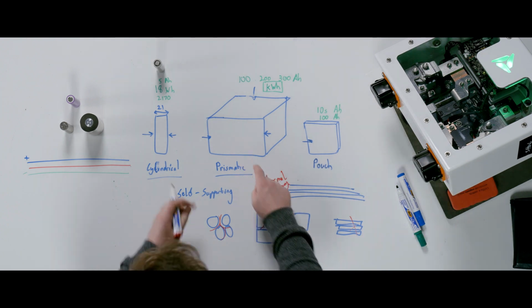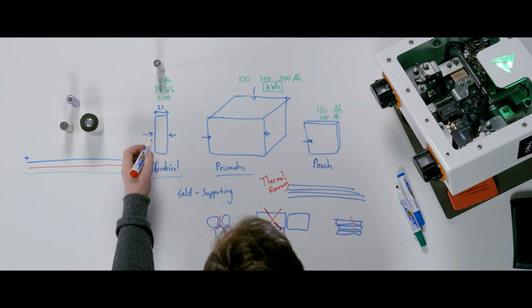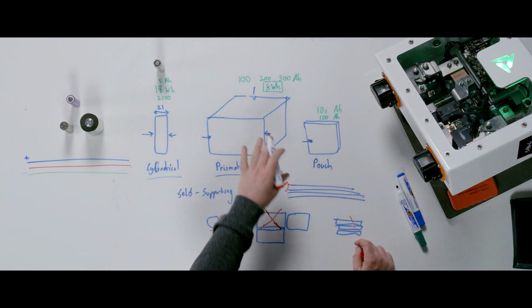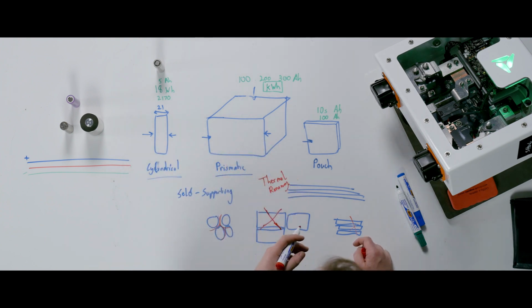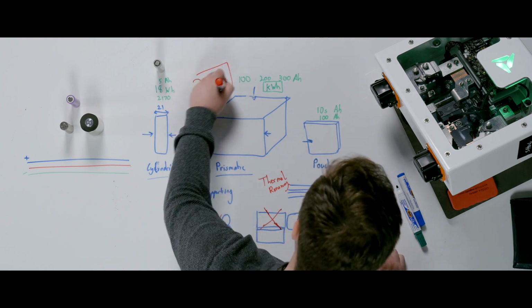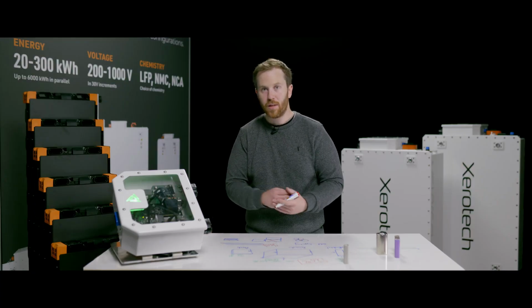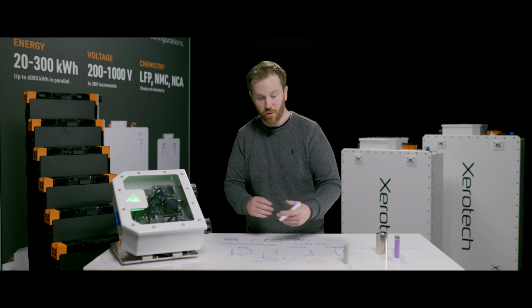The next piece is that we've spoken in previous videos of the importance of temperature. So heating and cooling a battery is really, really important because you want to keep it at 25 degrees C. Now the problem with large battery cells is getting the heat in and out. The thermal conduction from the battery, it's a function of the distance inside of the battery and the resistance.